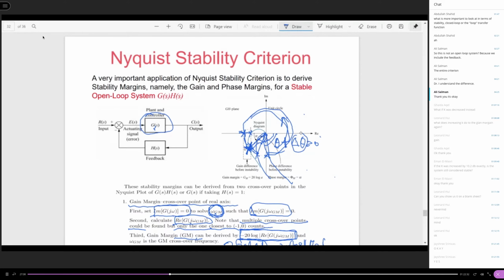So if you apply a positive delta t larger than 0, then you're gonna see this crossing over point with the unit circle stay away from the -1, 0 point, away and away, right? Don't forget, the -1, 0 point is also on the unit circle. Okay, so I'm gonna erase this, make it clear again. So you have a phase here, theta.